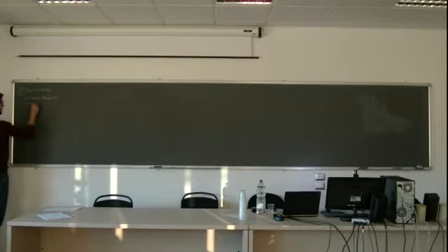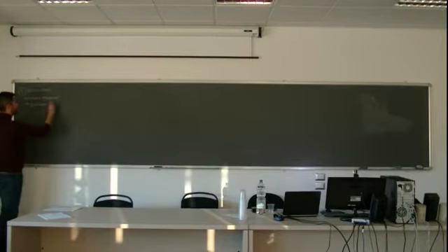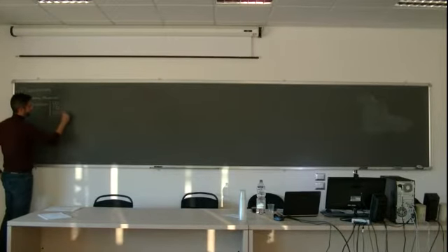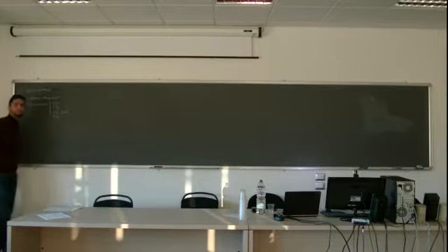Second, how many dimensions do you have? It's 3D, 2D, this is 2D axisymmetric, 1D. Try to avoid 3D as much as you can. I know that sometimes it's difficult and you need to go to 3D, okay. But if you can, what you are exploring, try to convert it into a case study or a numerical experiment